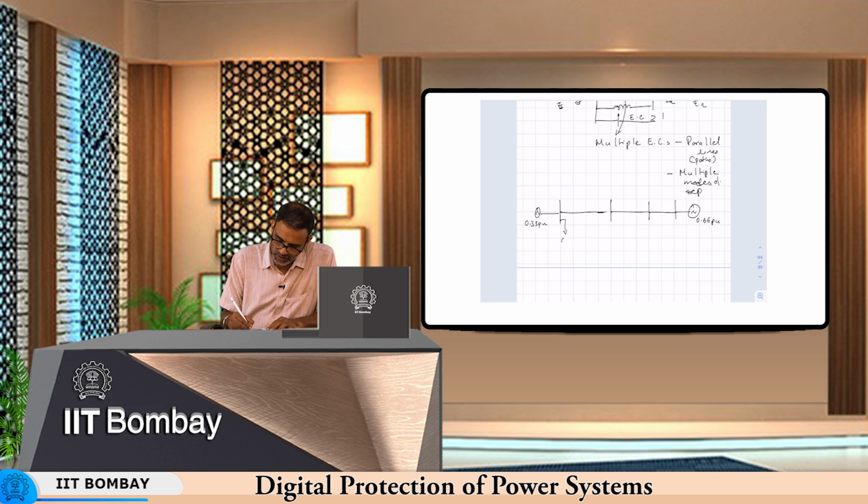Okay. The load here is 0.33 per unit, each has 0.33 per unit. So, roughly 1 pu, not exactly, but say 1 pu load and 1 pu generation. That is how a stable system operation is possible. So, load generation balance has always to be maintained.